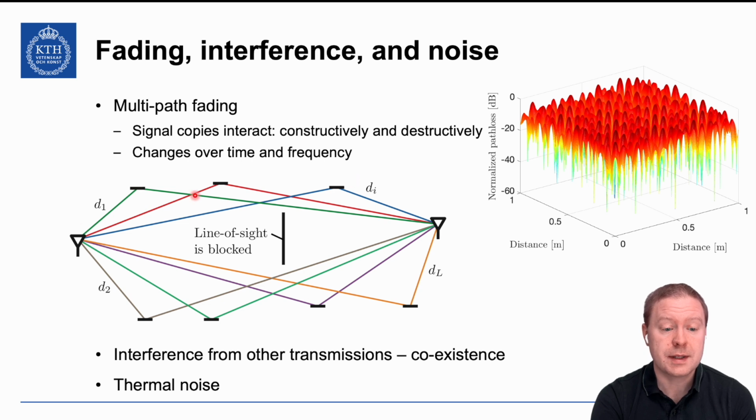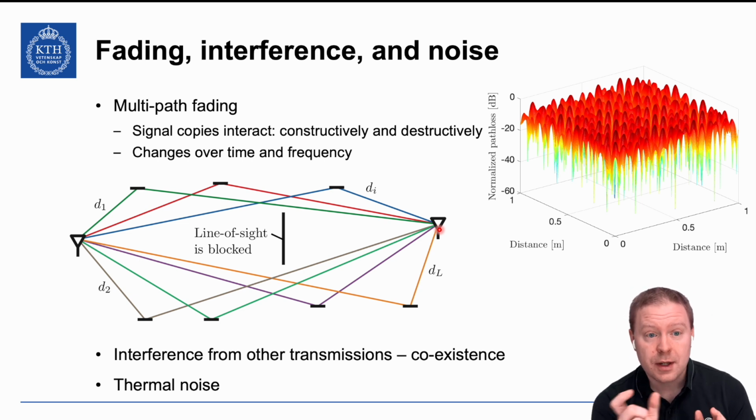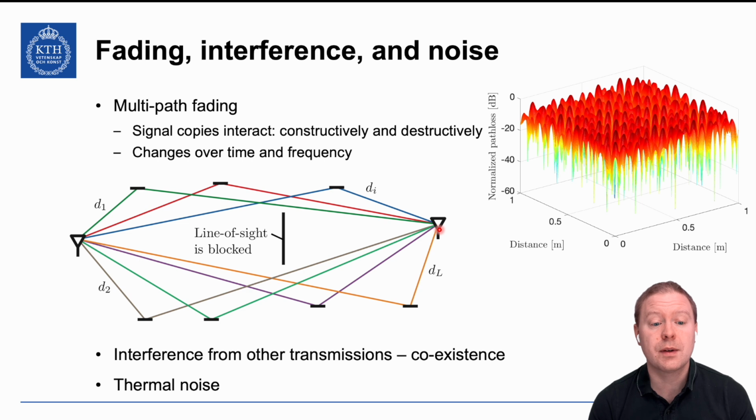And these different objects have different total lengths when you are measuring the signal propagation distance like this. That is creating different delays that turn into different shifts of the signal, and they can then add up constructively or destructively with the other copies coming from other objects when they are reaching the